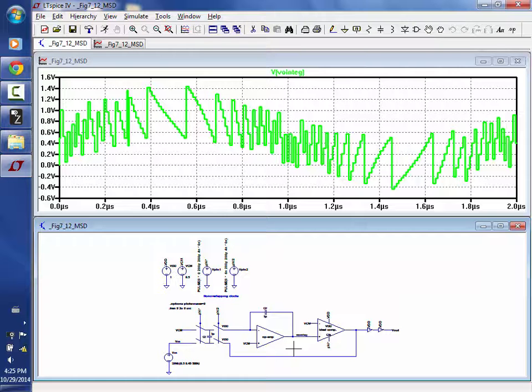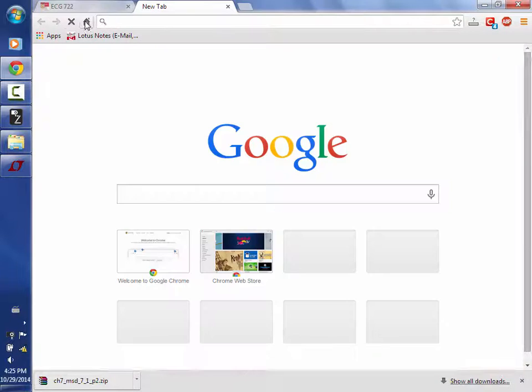So you do the topology, the stability. If you do a real high order with a large number of samples, it's really not practical to do a SPICE simulation. You'll find out even with what you're doing that it's going to be a little painful waiting for the simulations. I'm hoping that because it's continuous time and not switch capacitor and you design everything with simpler components, it's going to be faster, but we'll find out, all right? There are also limitations with the resolution in SPICE. It's tough to get beyond 10 bits without doing some things.